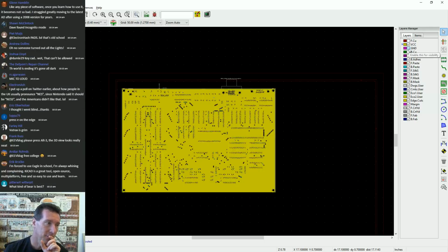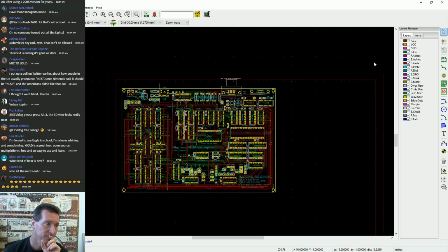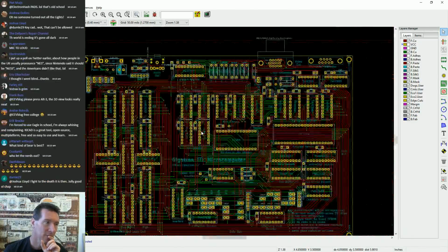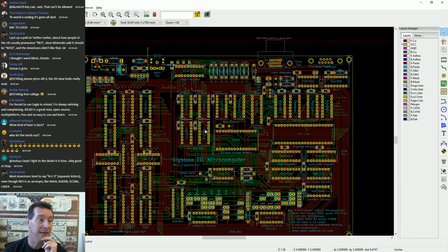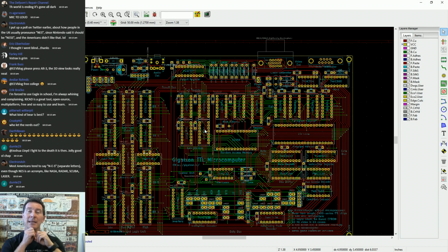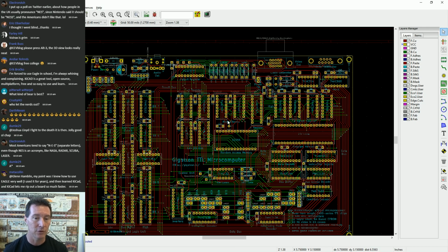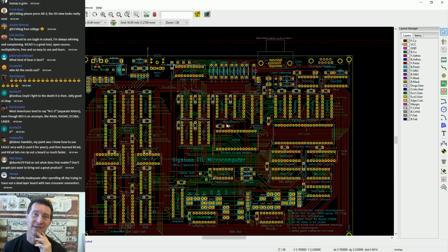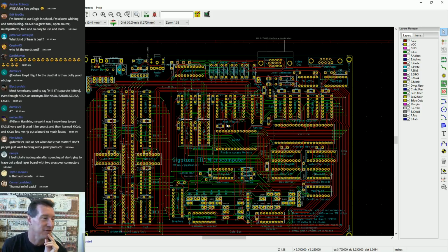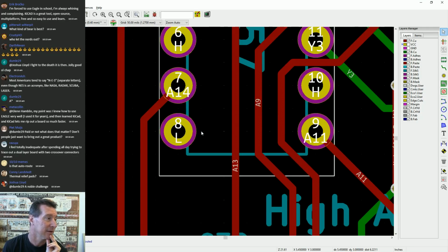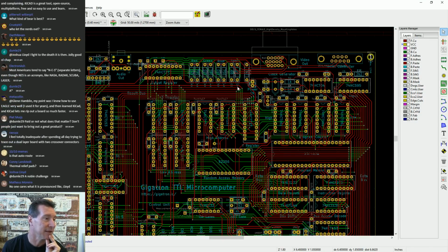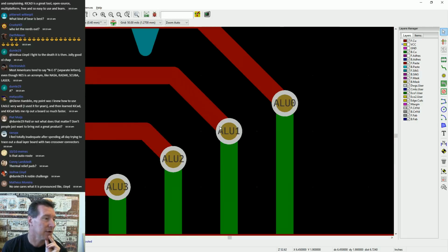Because the whole idea, for those who don't know, the whole concept of this is that I want to show the difference in EMC, in radiated emissions, of a 2-layer board with ground fill top and bottom, just like fill in copper everywhere and higgledy-piggledy, against a solid ground plane. I think this could be quite a good example of that. You can get a better example, but I'd have to design and manufacture one. I just have this one to hand, and I think it's good. It passes all the DRCs. I think we're good to go.